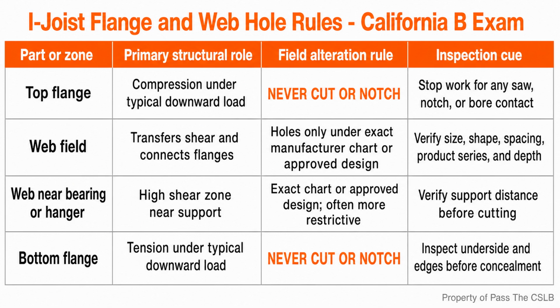Imagine a plumbing crew needs to route a large drain through an engineered floor. The shortest path places the opening close to a hanger. The crew has a hole saw ready, but the current manufacturer chart is not on site. The correct supervision move is not to guess from another brand, not to scale a photograph from the internet, and not to say that the hole looks centered in the web. I stop the cut and verify the exact product detail.